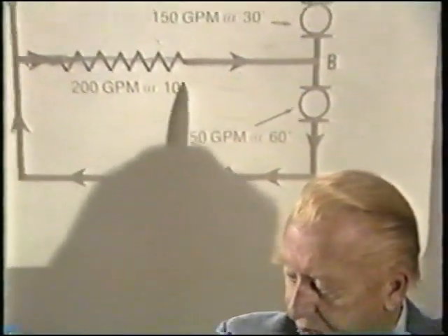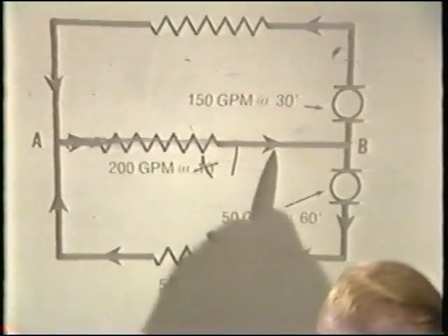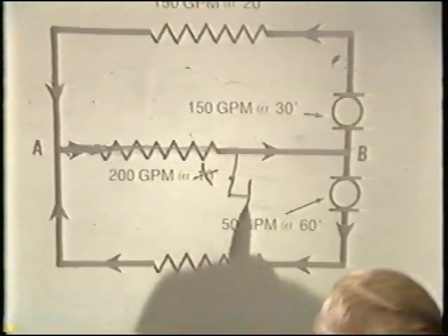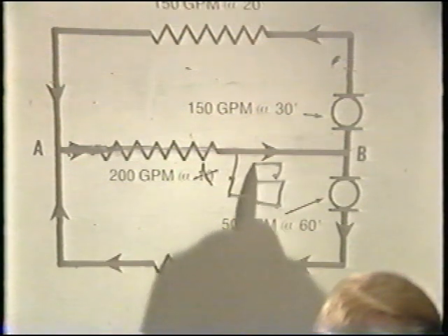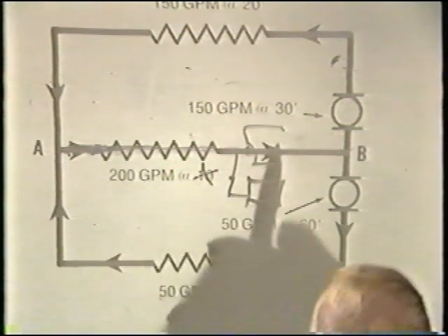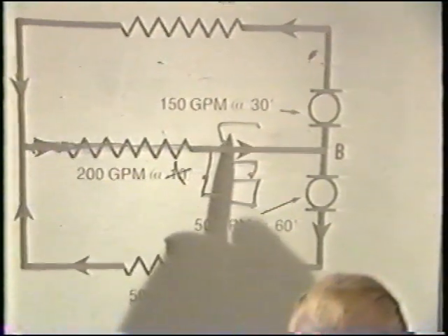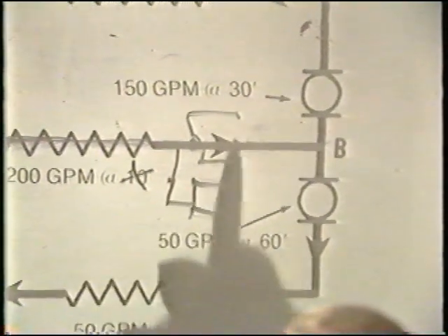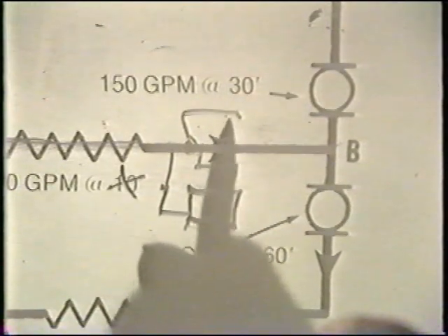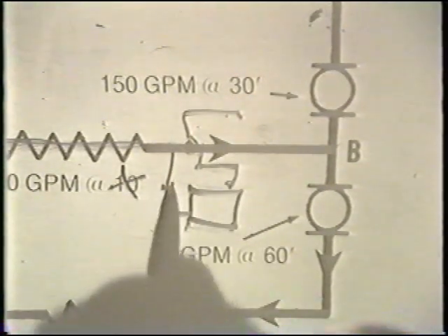Primary secondary pumping in the equipment room will eliminate a great deal of the otherwise difficult problems associated with zone pumping. This is because in primary secondary pumping, we would establish flow rate as through boilers and chillers through a section of piping in that piping common to both zones through a very low head loss common piping section.